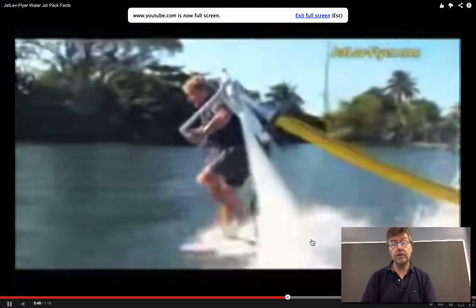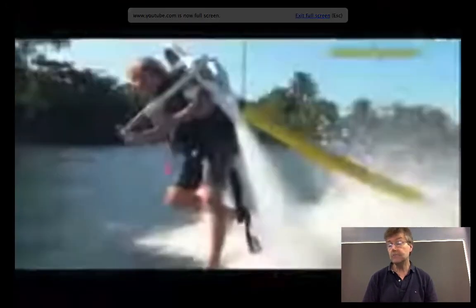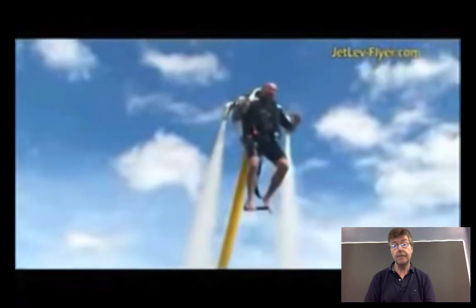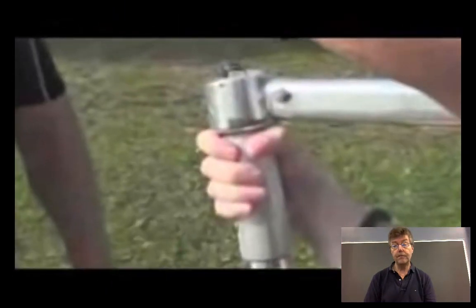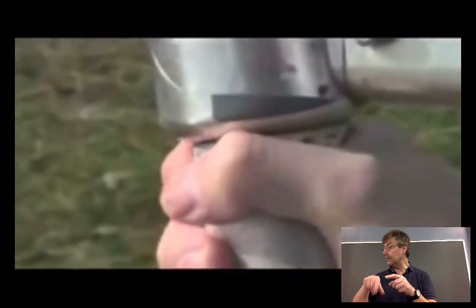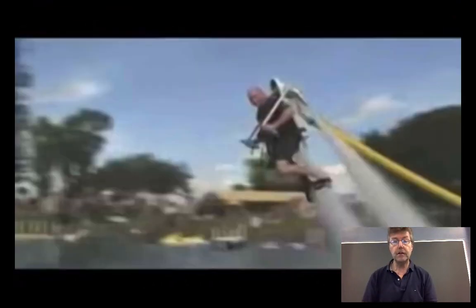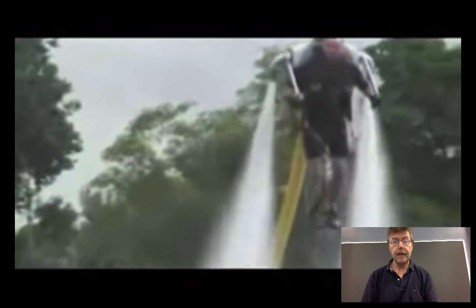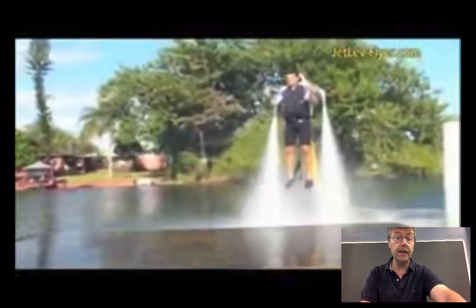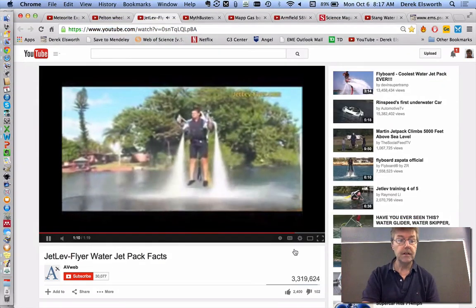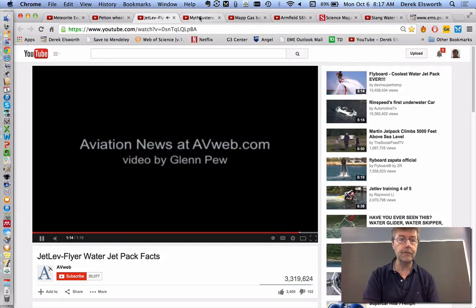And so now what Reynolds transport theorem allows us to do is perhaps do it a bit more elegantly, to solve the same problem and figure out, for example, what the velocity has to be that comes out of the base for the jet that is able to pick up the weight of a person off the ground. From that you could, for instance, dimension the pump that you might want to apply if you are designing such a frivolous piece of equipment, kind of a cool piece of equipment.